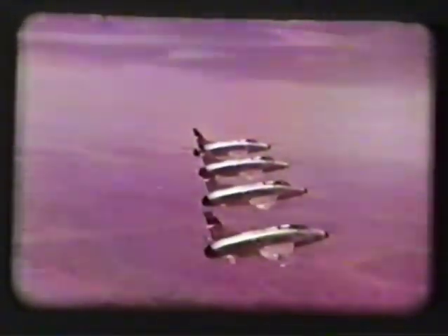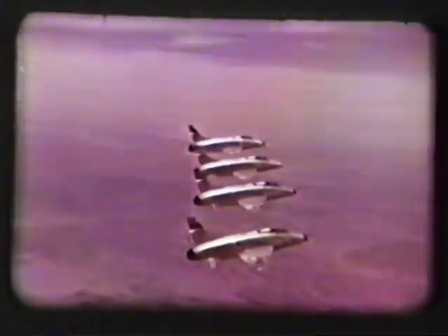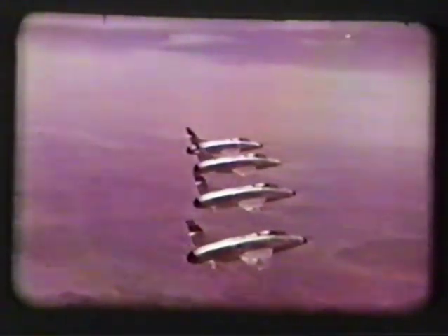All these improvements in design are reducing shock stall troubles in the difficult earlier part of the transonic range. Still faster flying is only possible when wave drag can be reduced, the drag caused by the shock waves changing kinetic energy into heat. A new design principle helps to do this. Area rule.